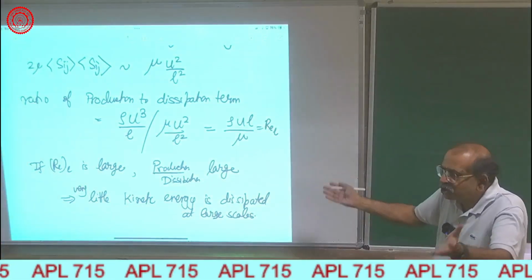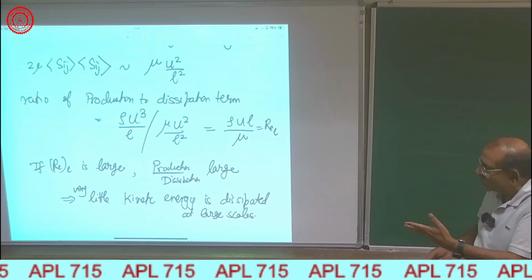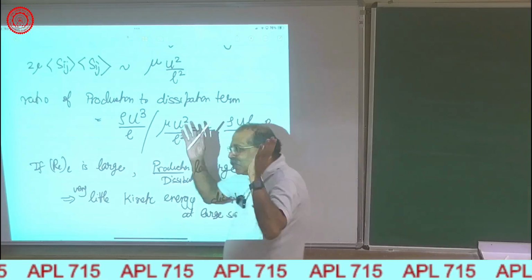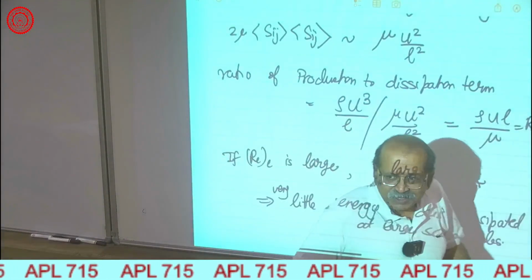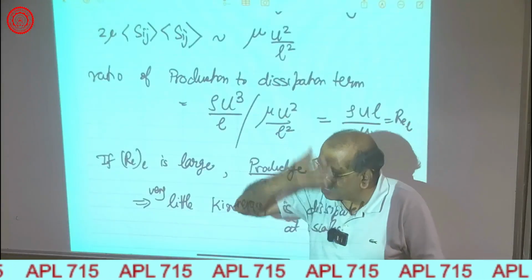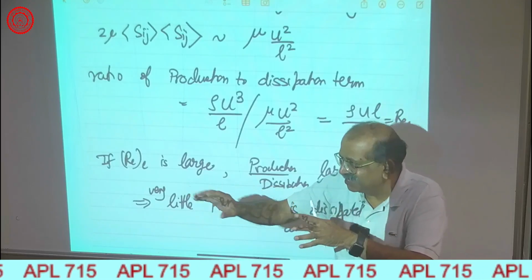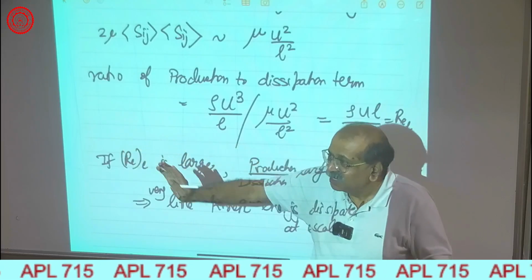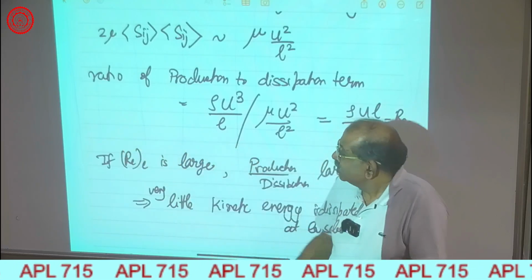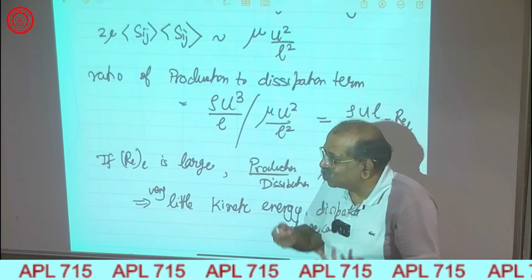that is redistributed. And so, in fact, that is what I was coming to. Let's go back to the total picture where we started from, or what we did in chapter 1. What we said was turbulence is there are large eddies there, and then they keep on breaking into small eddies. And we finally said that the dissipation takes place at the smallest scale. We didn't prove that. To some extent here, now we are saying that the equations also tell us the same